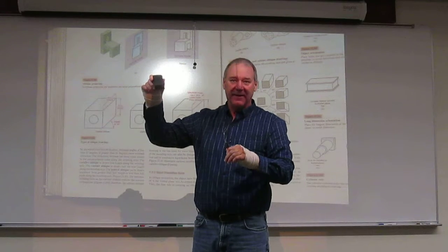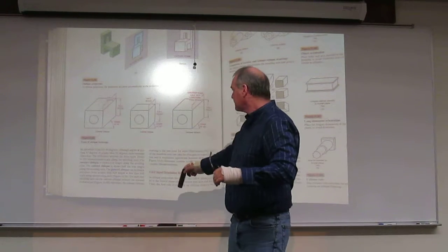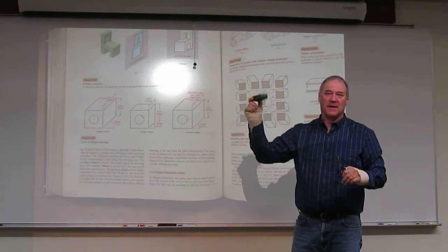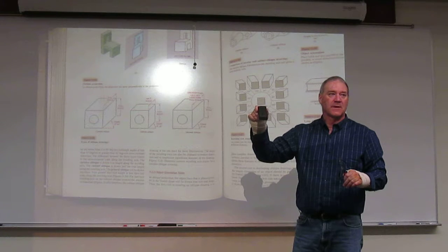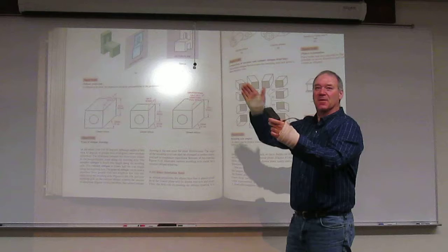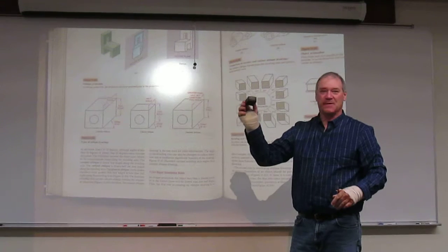I would probably immediately go to the second one, the cabinet, and if that one didn't work, then I would go to the general, just to get rid of that distortion, because this thing is going to look like it stretches on forever when you mesh it with that front view.